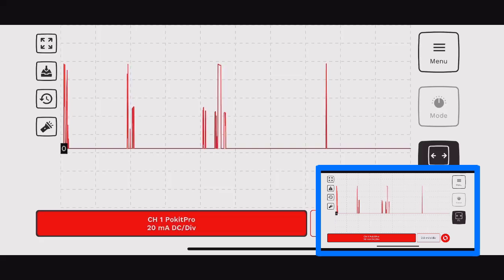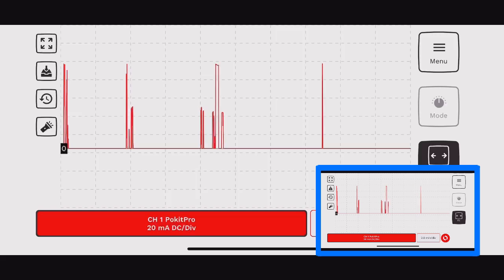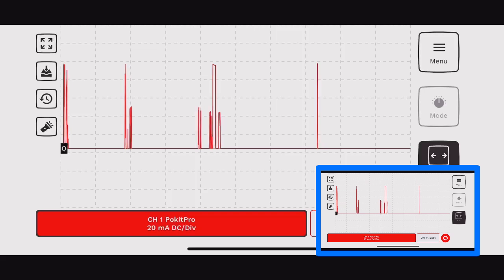You know this should be your target current, 170 microamps. Now you look at this thing and you go, oh my, okay, I've got 170 mics on this one, but this one I'm reading 220. All of a sudden you see it climb, 300, 600. That's the bad relay. The one that's doing that is the bad relay. These are hard to find, but not impossible.